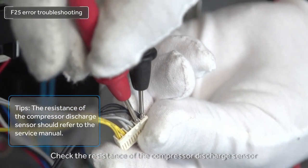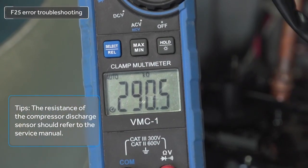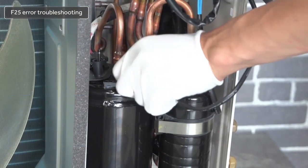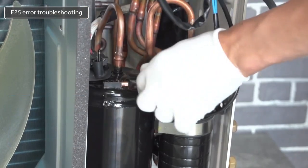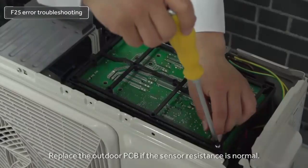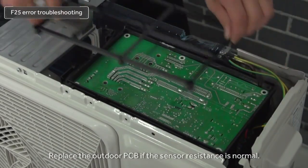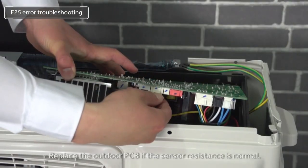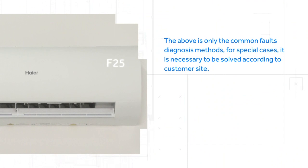Check the resistance of the compressor discharge sensor, the black part of the sensor terminal, and replace it if the resistance is not normal. Replace the outdoor PCB if the sensor resistance is normal. The above are only the common fault diagnosis methods. For special cases, it is necessary to solve them according to the customer site.